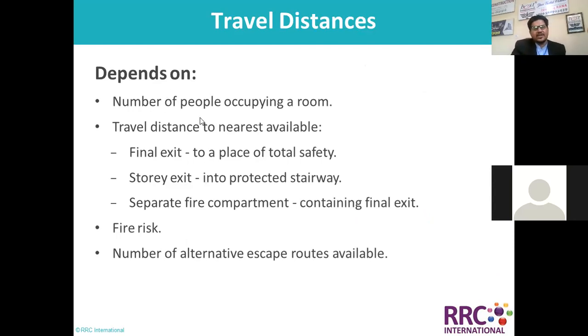Now, it depends on the number of people occupying a room and the travel distance to the nearest available exit. But make sure the final exit is to a place of total safety, with storey exits and a separate fire compartment containing the final exit and fire risk, and the number of alternative escape routes available. And it should also be shown, well ensured, on your fire evacuation map.